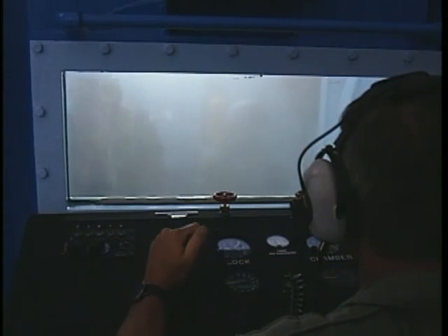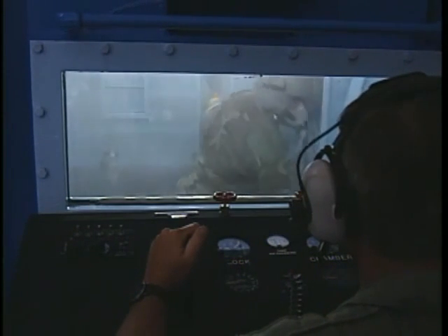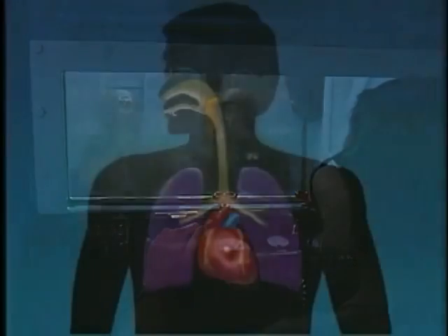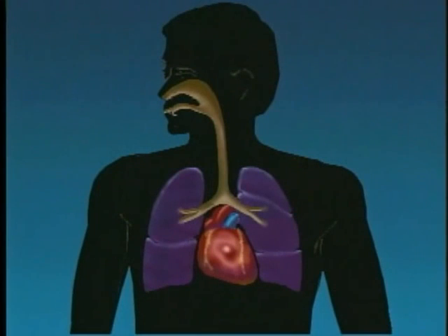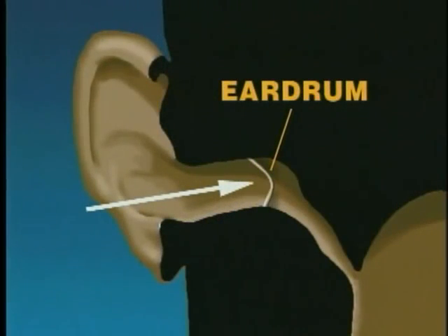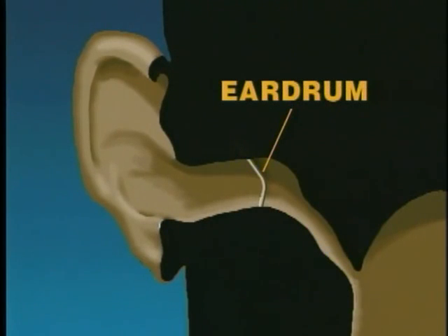Due to the rapid drop in temperature and the change in relative humidity, fog will often form during a decompression. The human body will also be affected. A sudden low pressure outside the lungs will cause air to escape through the nose and mouth. Differential air pressure on either side of the eardrum will automatically equalize. Other hazards include exposure to wind blast and extremely cold temperatures. The pilot should be aware that decompression of a small volume cabin is more hazardous than a large one.